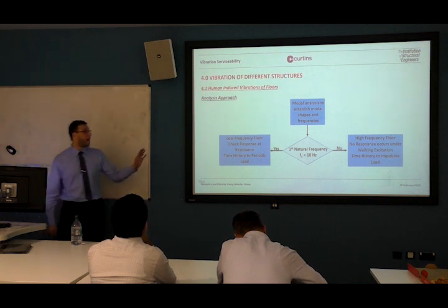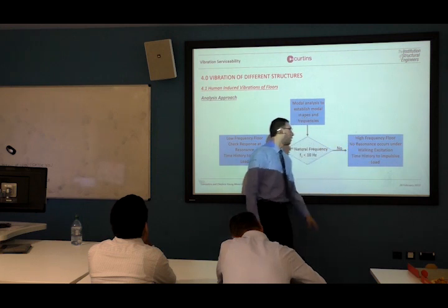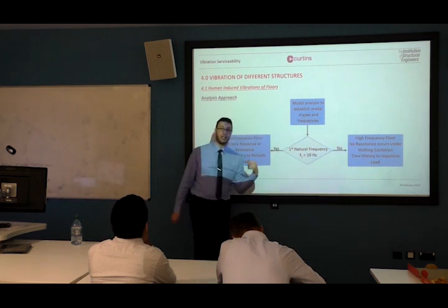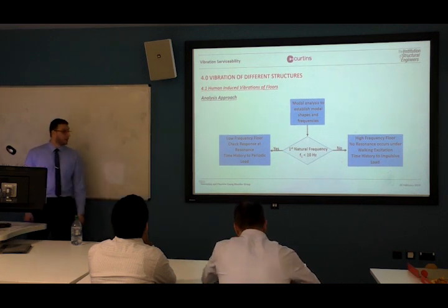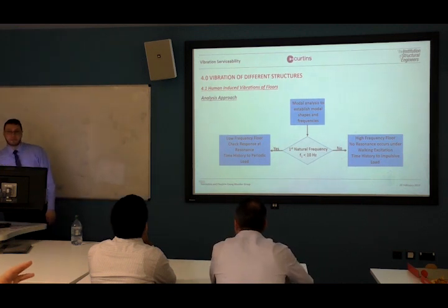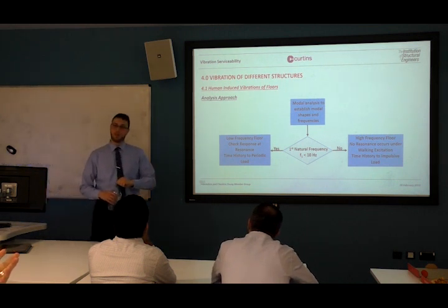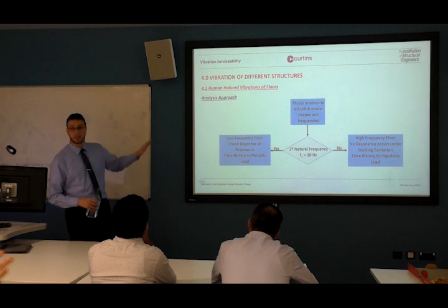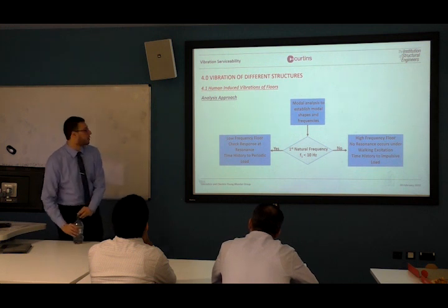So that's why I'm not going to talk about loads on these high frequency slabs, but there's guidance which talks about how we get them. But what we're going to touch on, the analysis here just includes the mass of the slab, isn't it? No loads we have at the moment. At the moment it's just modal analysis. Yeah, the natural frequency of the slab itself. Yeah, at the moment it's only natural frequency.